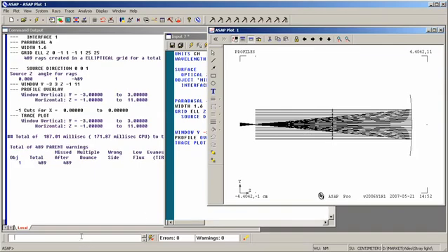We tell ASAP to move the rays to the plane z equals 0, which is where our nominal paraxial focus is. We set up a window yx, which is normal to the direction of our rays. I happen to know that this window will be too large by default, so I tell ASAP to bring it down.